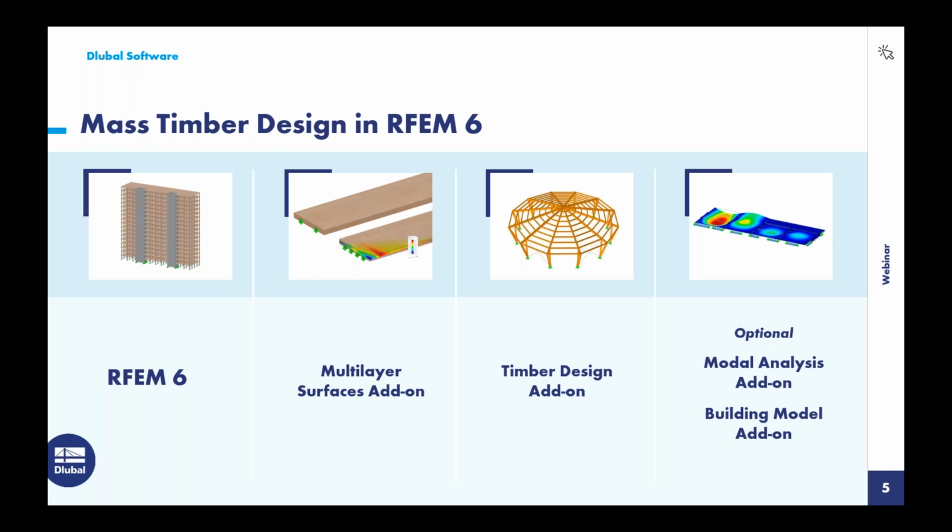However, if we want to model CLT panels, to individually define the layers for a user-defined layup or to import in the CLT products from the various manufacturers, we will need the multi-layer surfaces add-on. This will make more sense as we go through our examples today. The timber design add-on allows us to carry out the full design of the timber members and the CLT panels according to that CSA standard.